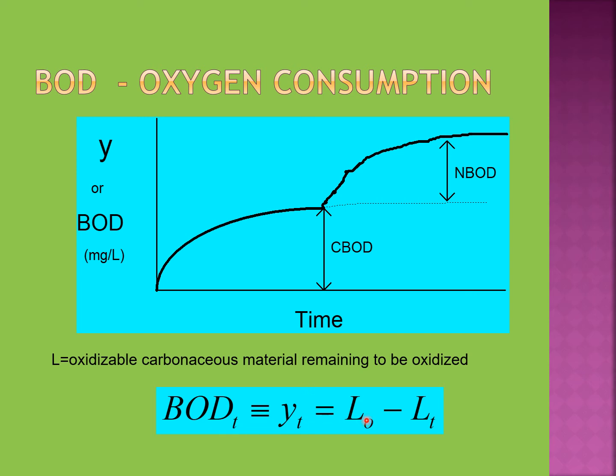BODt equal to L0 minus Lt, where L0 is the BOD loading at the initial or starting point, as initially the BOD is greater, and after a certain time t, the BOD loading will decrease as oxidation continues. This Lt is the BOD loading after any time t.